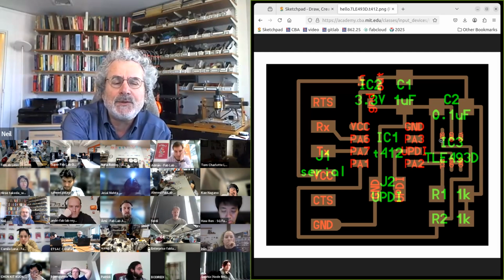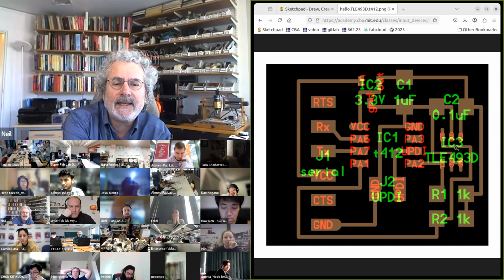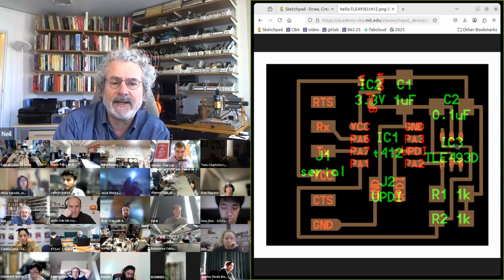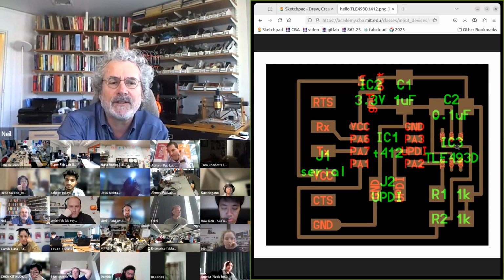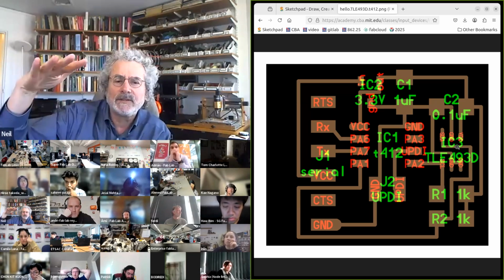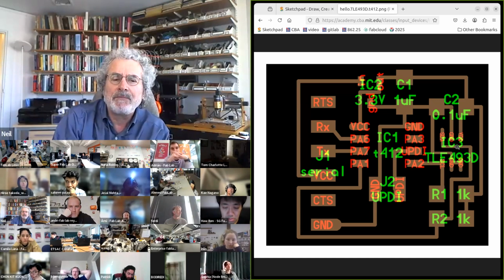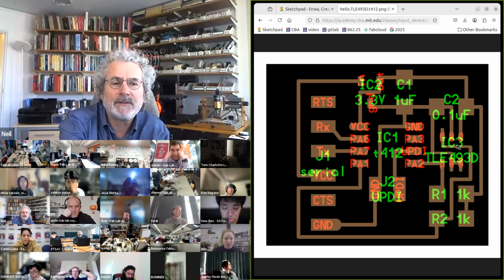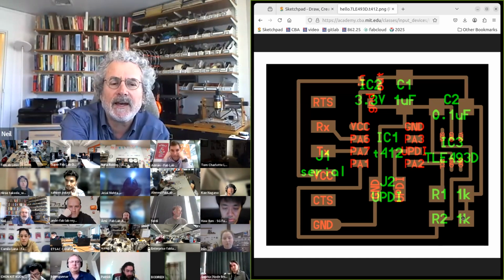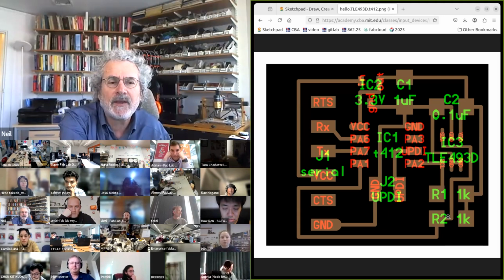And then I2C has 2 pins, SCL and SDA. One is clock, one is data, and they can go in either direction. And since they go in either direction, the way it works is you pull down with a pin and a resistor pulls up. So when you use I2C, you always have a pull-up resistor that goes to the power supply. So I've got my 2 pins coming in.